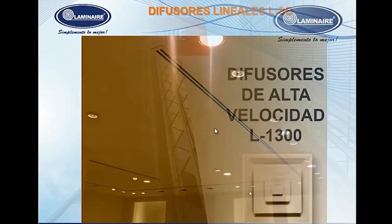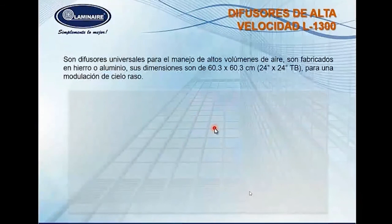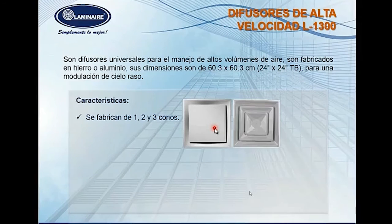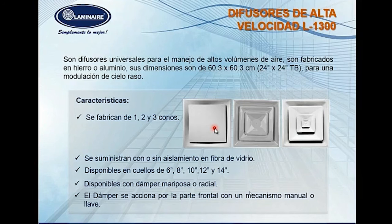Other diffusers that are very important are the high velocity diffusers, L1300. These diffusers are universal for managing high volumes of airflow. They are manufactured in steel and in aluminum. Their dimensions are used for modulated ceilings, 60 times 60 or 24 by 24. They have different cones, for example two cones, three cones, diffusers with isolation in fiberglass. They have necks of 6 inches, 8, 10, 12, up to 14 inches. They are available with a radial damper. The damper is always activated from the front part with a manual mechanism or with a key.